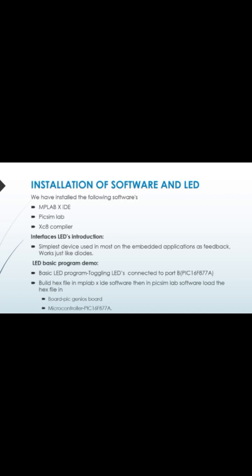Now the basic program is toggling of LEDs connected to port B of the PIC microcontroller. We are building a hex file in MPLAB X IDE software, then compiling in the XC8 compiler, then in PICsimLab software, loading the hex file with the PIC board and the PIC microcontroller 16F877A. Okay, this is the basic program. We are using the PIC board and the PIC microcontroller 16F877A.